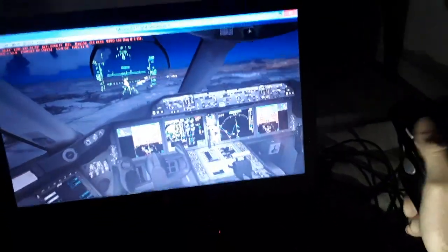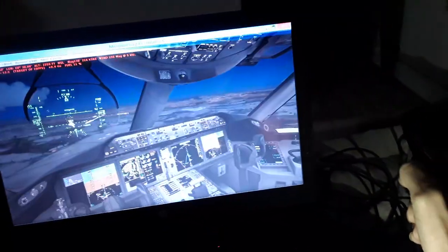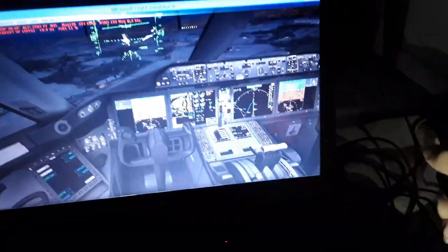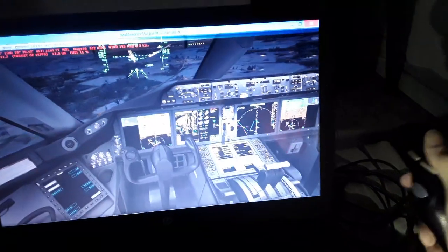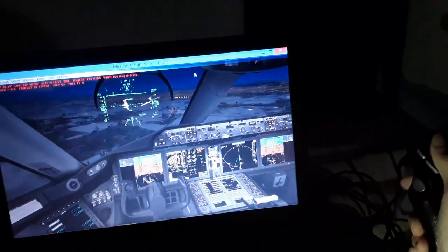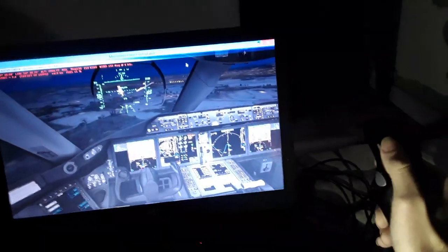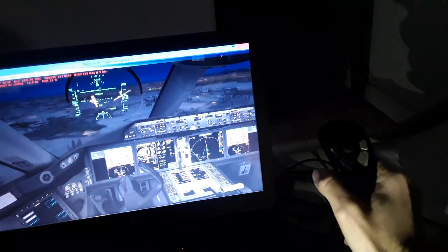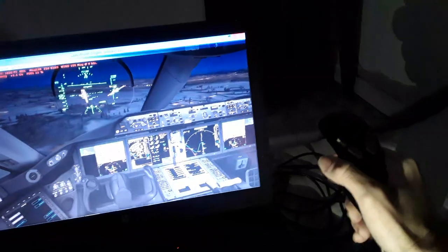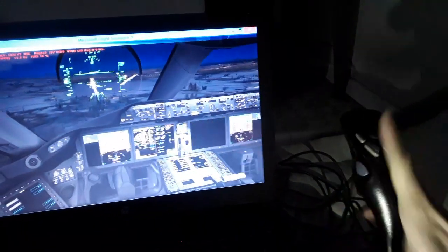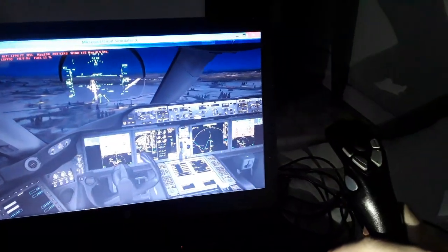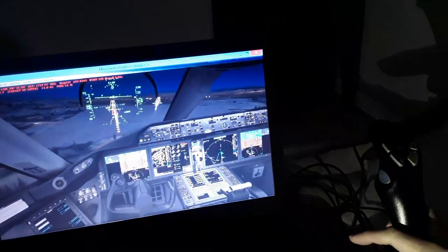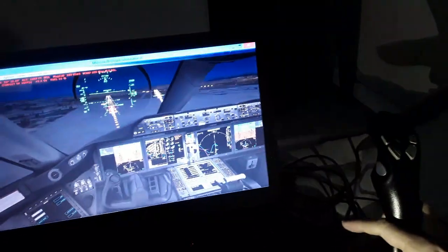And you can see a little bit more idle thrust right now. Again align with the rudder pedals, right rudder now, left rudder now. A little bit more thrust. And we have a lot of side wind, which blows the aircraft to the side, away from the runway center line.